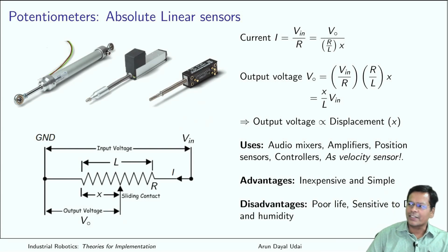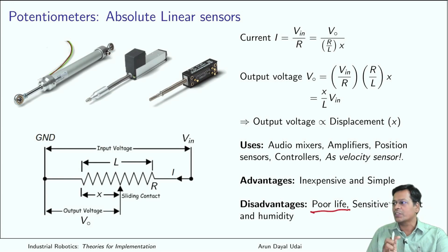Disadvantages are definitely there. They have very poor life, because this slider is going to rub against your resistance strip. So with time it goes a little noisy because of the wear that is happening.